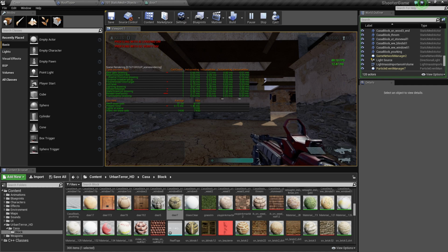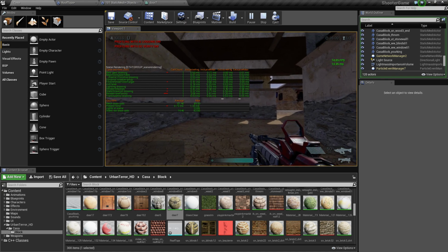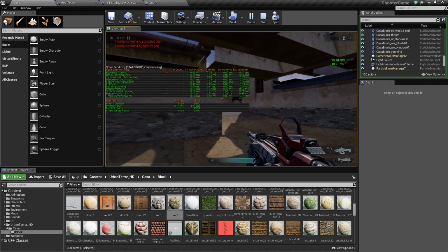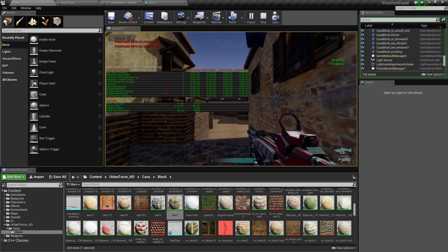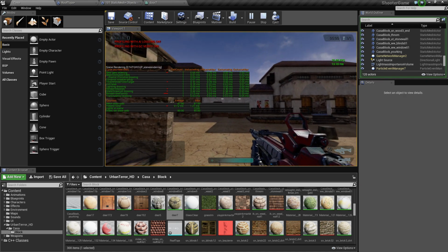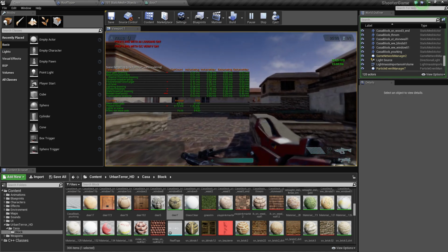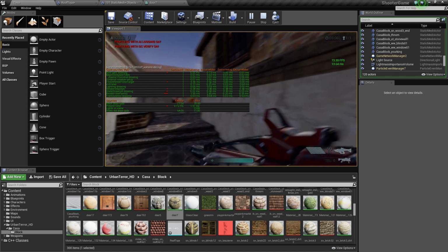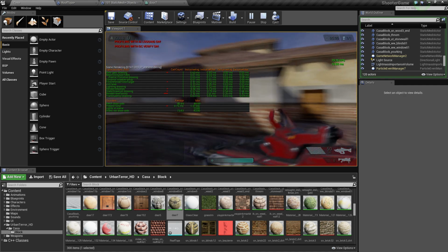Okay, this is what's going on and occurring in our scene. As you can see down at the bottom, the average... to be honest, I have not fully figured out what all these numbers mean. I've got to go through the documentation, but the things that stand out are anything relating to draw calls. Under mesh draw calls, it says 87. Is that for real? Are we actually looking at the number of draw calls? The happy safe spot is a max of 1,000, so you can see that our draw calls are significantly lower.